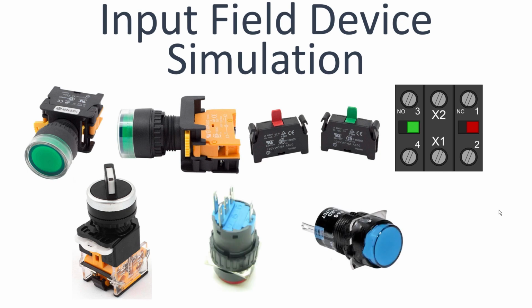This is, I think, a 16 millimeter. It's smaller. I showed you the back side of it so you could see that the 2 outside soldering lugs, if you look close, the one that you can see has a plus sign on it, and then on the far side you can't really see it, but hidden back there there's a minus sign. This is the LED. This is to power the light inside of it. Then you have 3 terminals for the push button. It's momentary. You have a common, normally open and normally closed.